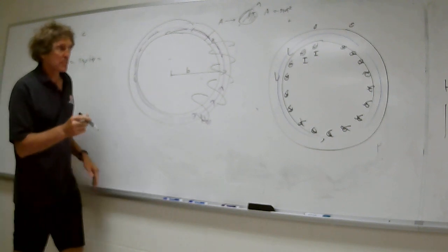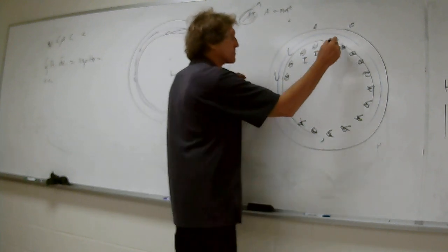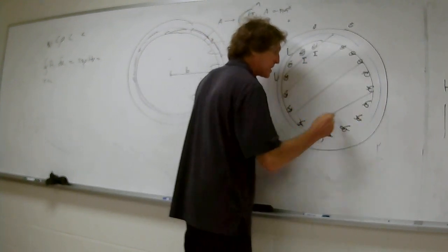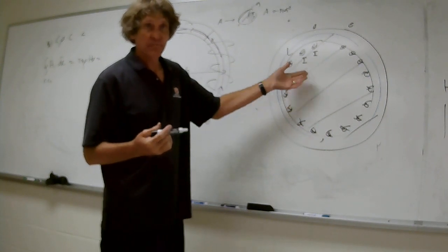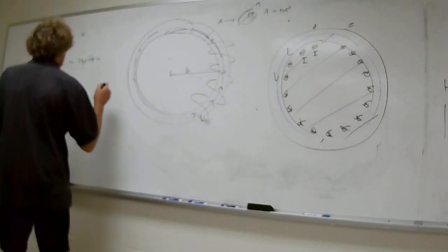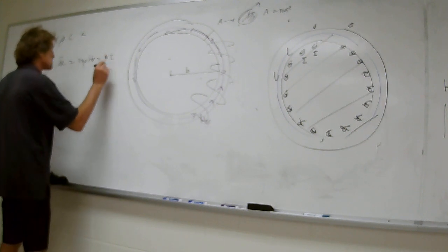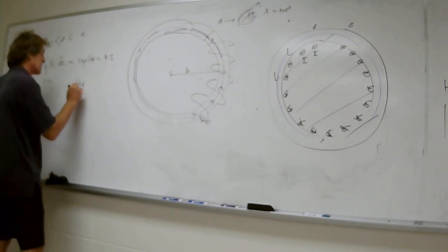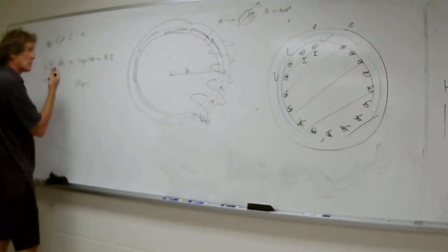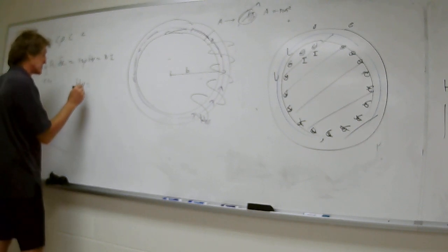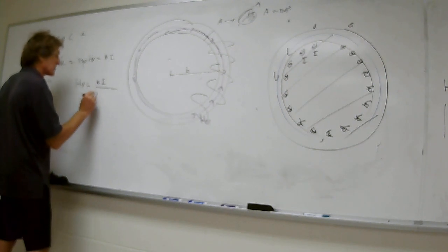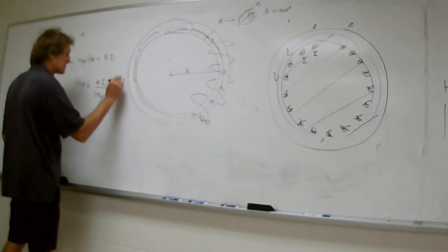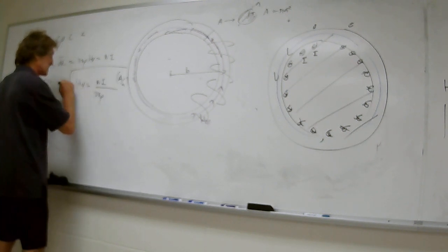How much current is penetrating this loop? And this is the area of the loop. It's this entire thing here. Well, it's I times the number of turns, so it's going to be NI. So that means H phi when you're inside the solenoid, or toroid, is just equal to NI over 2 pi rho. And that is it, and the units are amps per meter. But this is the H field.